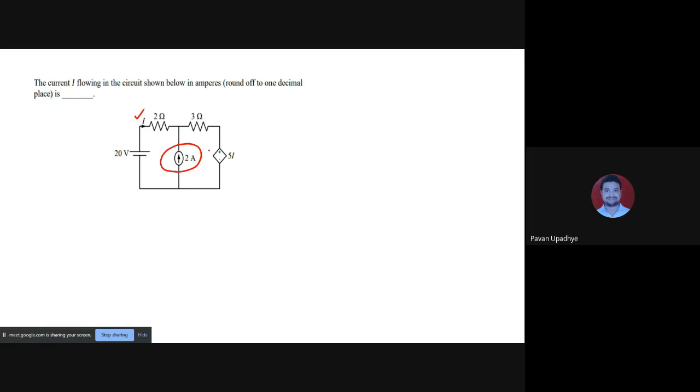And look at this, the circuit consists of one dependent source, because it is a diamond. As I said, the diamond shape of sources represents dependent sources, and inside it, if there are polarities positive and negative mentioned, then it is a voltage source. So in that case it is a dependent voltage source. And instead of this, had there been a diagram of such a kind wherein an arrow is mentioned, then it would have been a dependent current source.